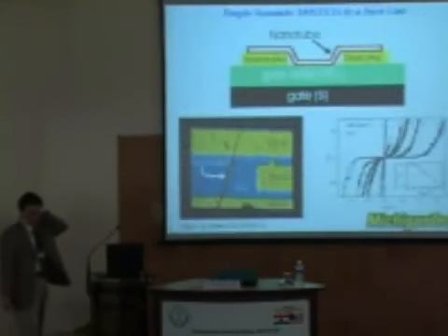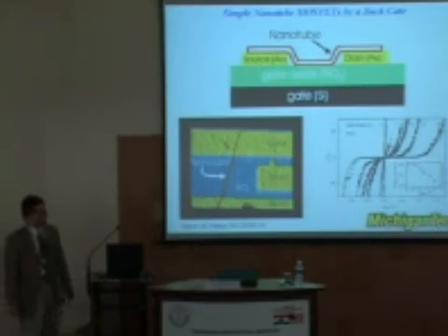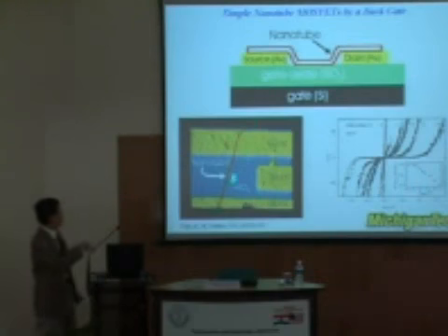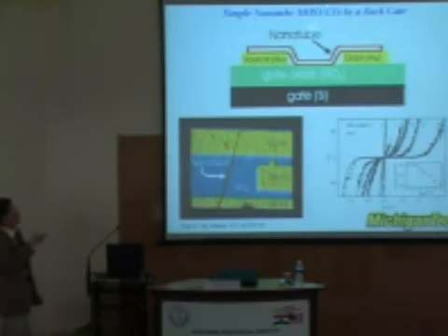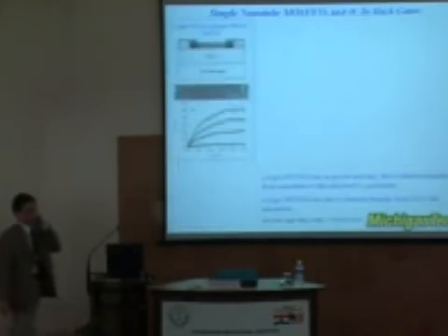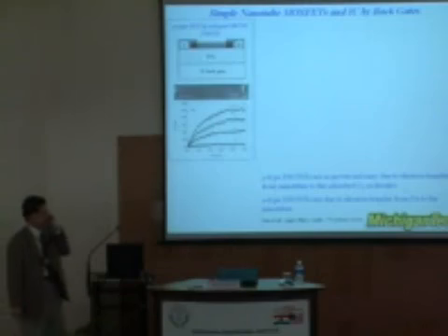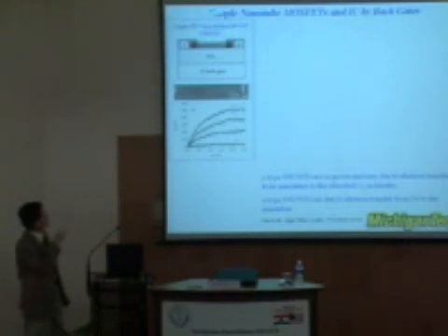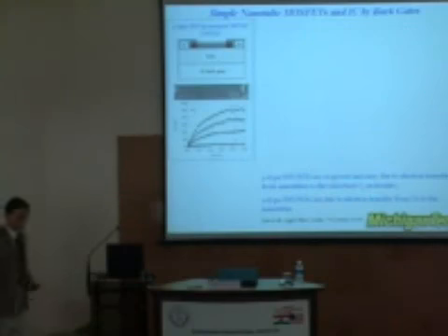This was the first field effect transistor ever made in the world, using a piece of carbon nanotube, a single-wall nanotube, laying across 2 electrodes, and the whole cross-section structure is shown here. Basically, it forms a transistor with source, drain, and gate electrode. And you can see the switching is pretty nice. What progressed further from here is that in 2001, you started to see that carbon nanotubes always behave like p-types. And in fact, this is basically because of the adsorption of oxygen molecules.